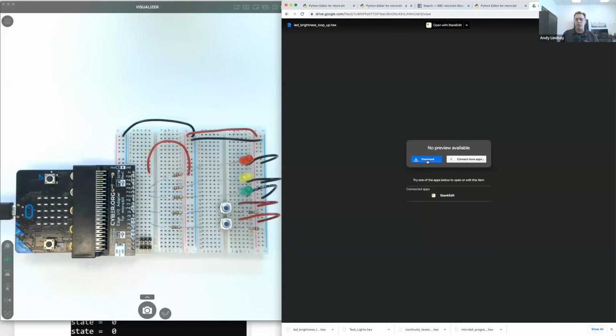And if you're looking straight down on the top of the dome of the light emitting diode, you might be able to see it more clearly. Will wrapping your hands around it help? Yes, thank you to whoever chatted that. If you wrap your hands around it and look down, that's another way to see it. And there was another question: is 1023 the max? Yes, 1023 is the max of brightness control. 1024 would be if you simply said write digital of 1.